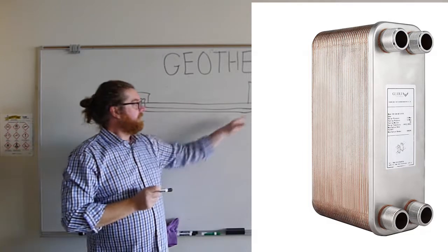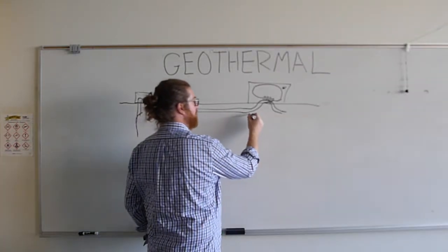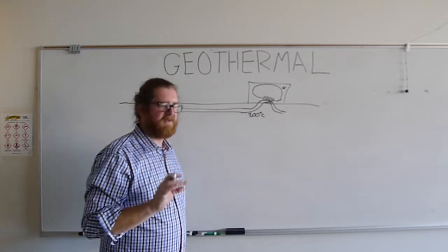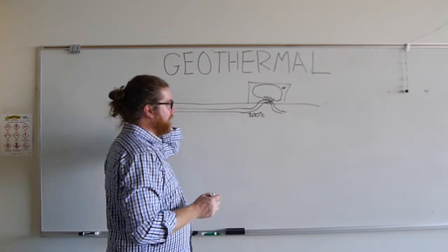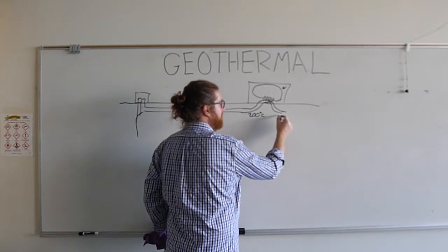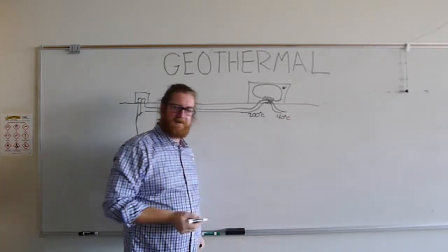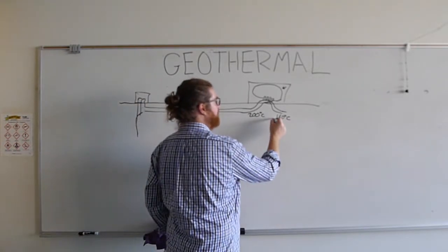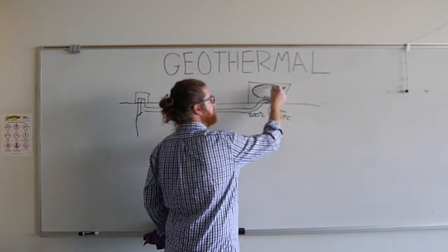And so in this case, the Boise Geothermal System might be selling you water that comes in at 200 degrees C. I think it's a little bit colder, like 180 actually, but we'll use 200 to keep the numbers simple. And then when the water leaves your area, it might be coming out at 160 degrees Celsius. And that difference, that 40 degrees Celsius, you used in your own system here in your building.